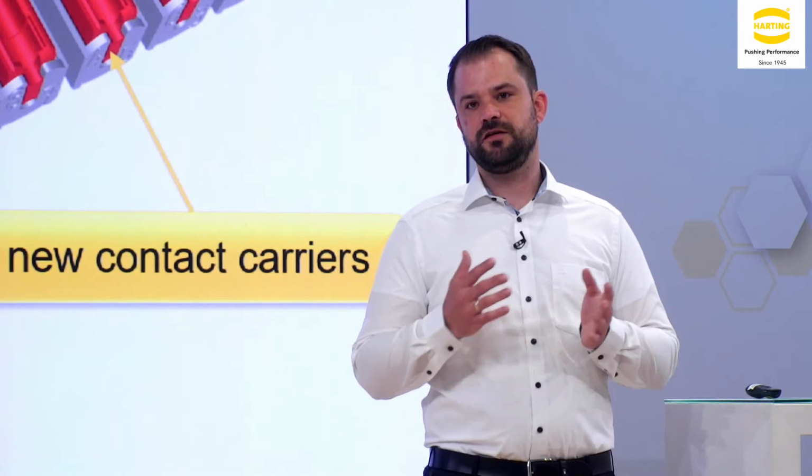And there's another point that is noticeable. The 100-meter channels, meaning Cat 5, 6, and 7, can implement 4 connectors, and the channel of Cat 8, which is only 30 meters long, can only implement 2 connectors.